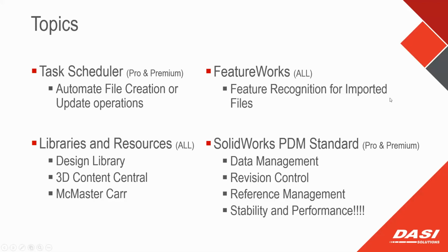FeatureWorks will run feature recognition, so if you need to do modifications to files, even in a small amount, just simply isolate the feature recognition process and parameterize those things that you need to deal with. And then lastly, SolidWorks PDM Standard, which is included in all SolidWorks Professional and Premium licenses. Revision control, check-in, check-out, data management, and definitely stability and performance by not working live across the network, only amplified by a multi-user environment. You're working locally, and you're minimizing network traffic as a result of the mechanism that it is.